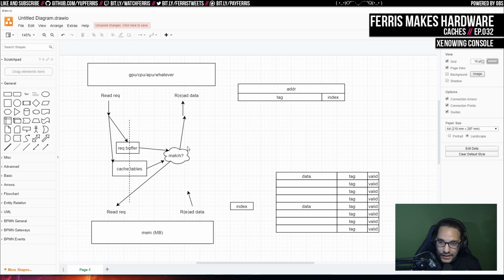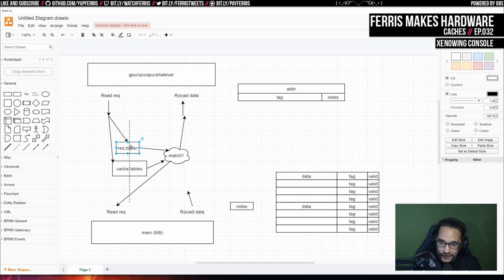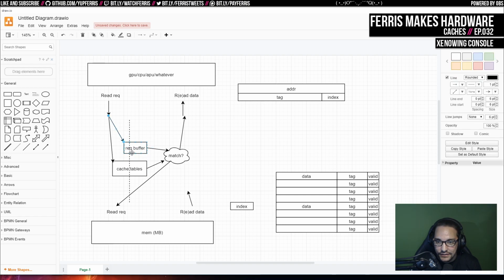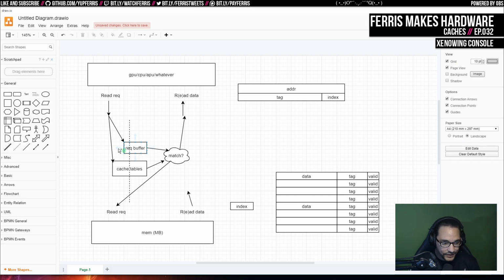And you want to do things like, if we have a request in this buffer, that means we issued a request on the previous cycle. In fact, I can send this to here to make sure it's clear that it's on this cycle. So if the request buffer is actually full, then we know that we had an issue last cycle.